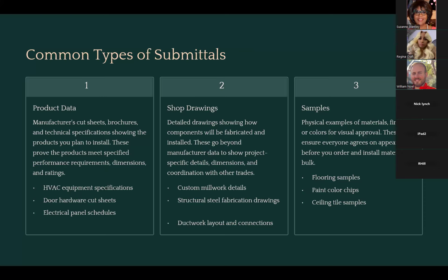And you're going to send that upstream to get approved, and that's going to protect you again when you come in and your cabinet may be an inch and a half longer than the overall dimension, but that's because of the size of the cabinets that make it up. You can't do the exact dimension that's on the drawing, and that's why you would turn in a shop drawing to protect yourself from that difference in the contract drawings and your submittals.